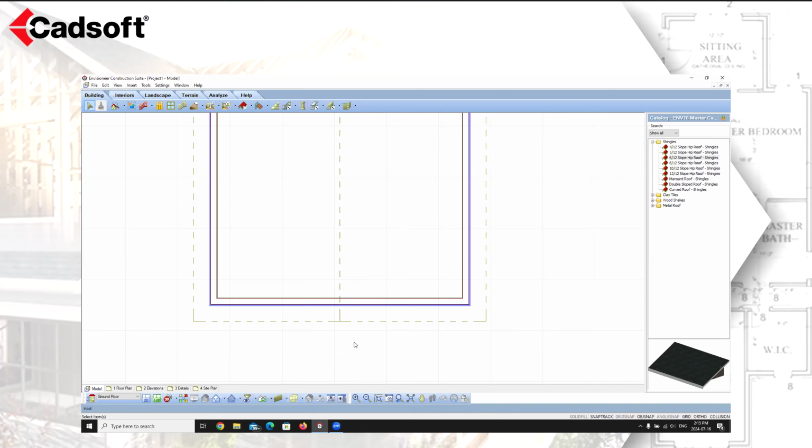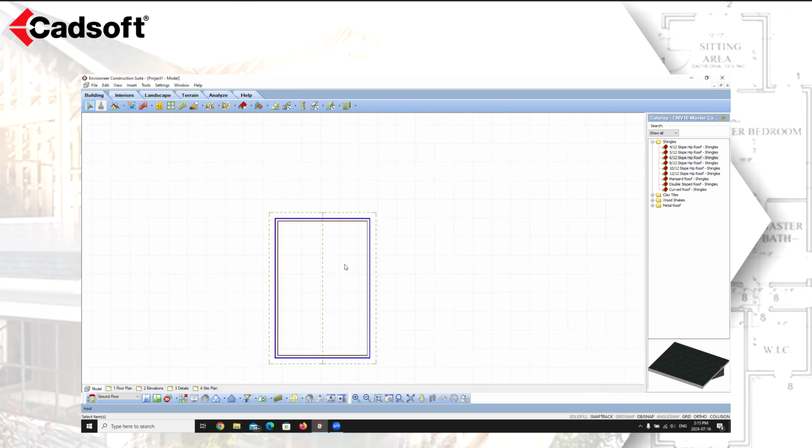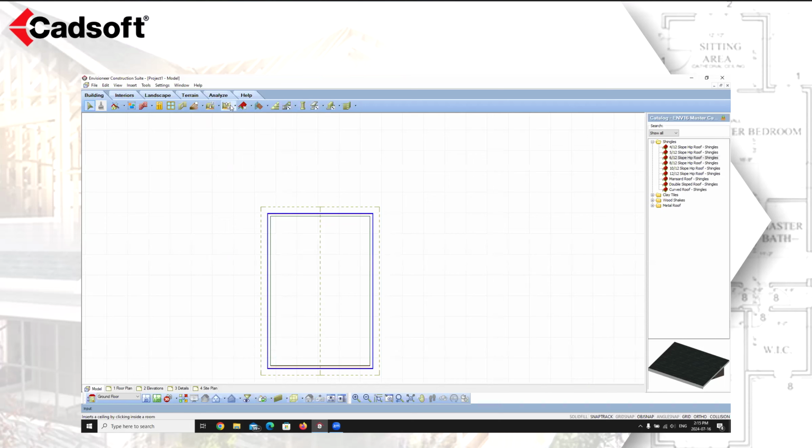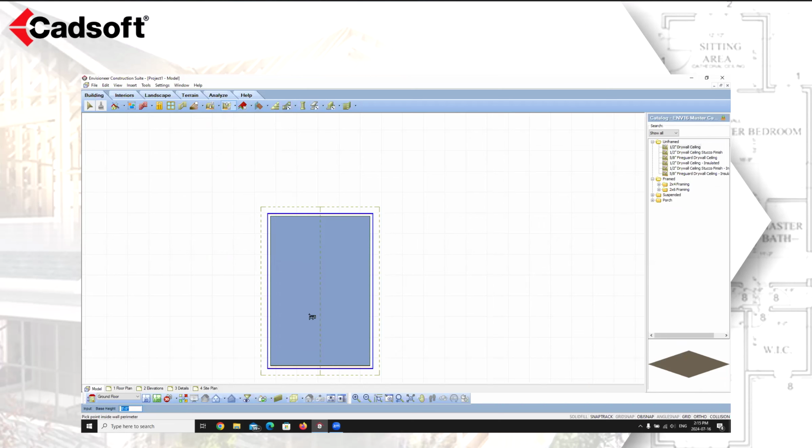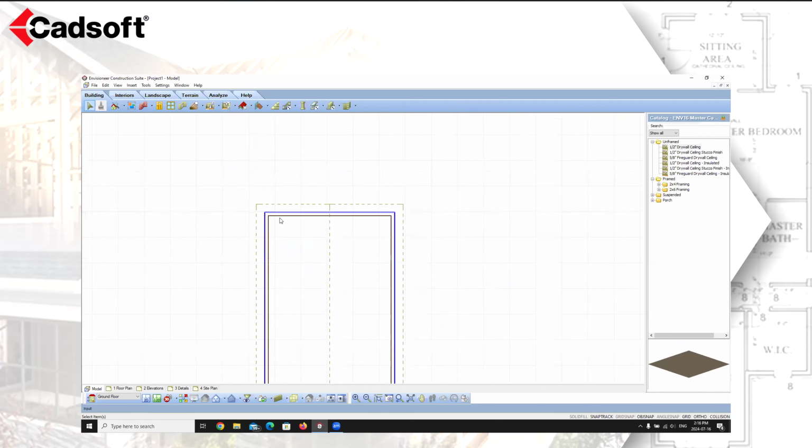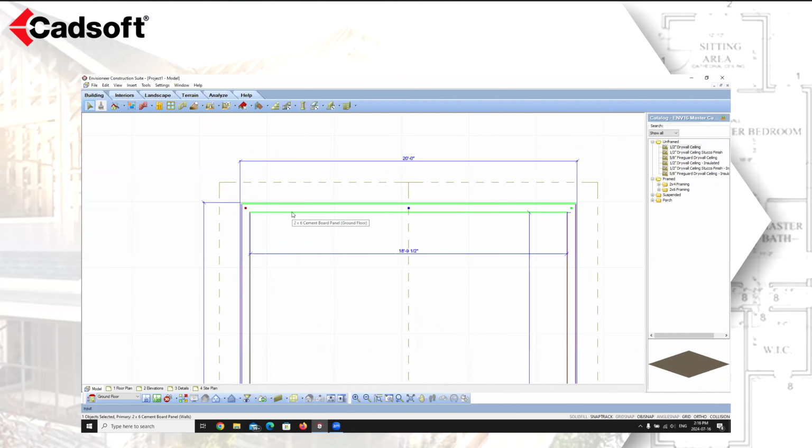profile. It also recognizes any ceiling surfaces beneath the roof and will alter the profile of the bottom chord to accommodate them. So let's add in a ceiling really quick into our design. So we're going to go in, we're going to drop in a ceiling. So go ceiling by room. It's going to use a 1/2 inch drywall ceiling. I'm going to drop that right into the middle of my design. That adds in the ceiling.